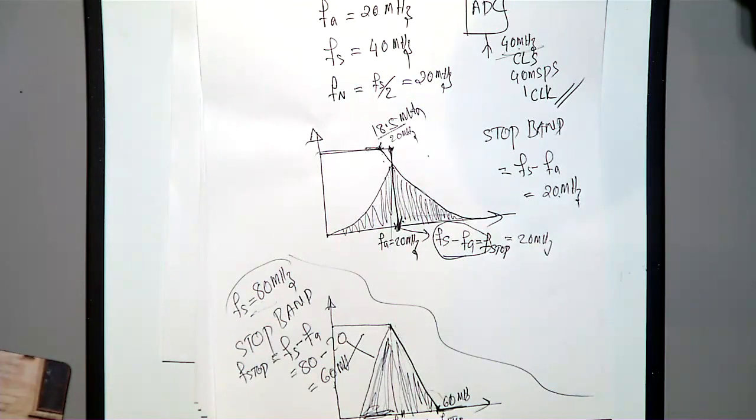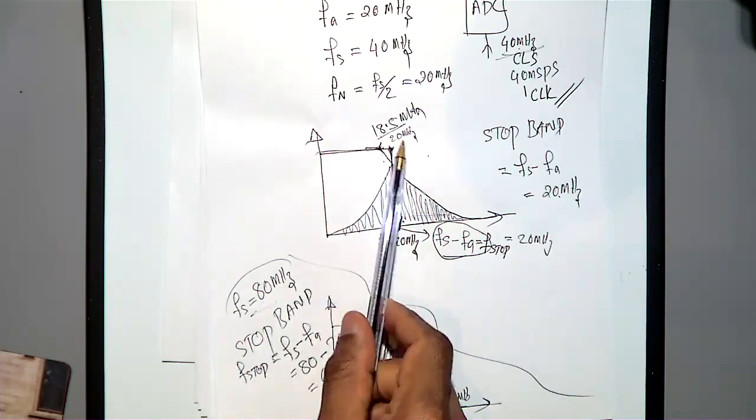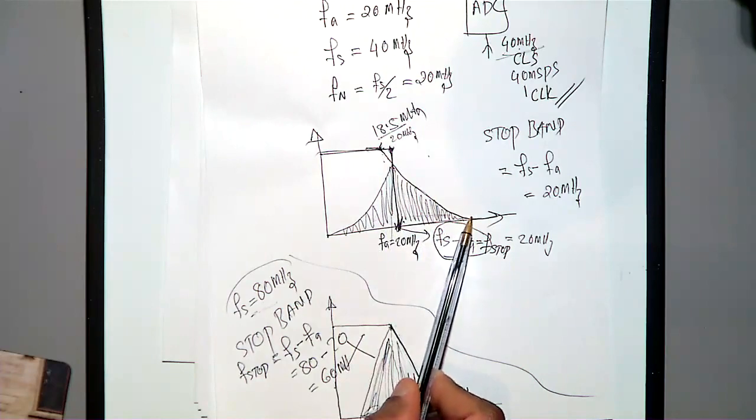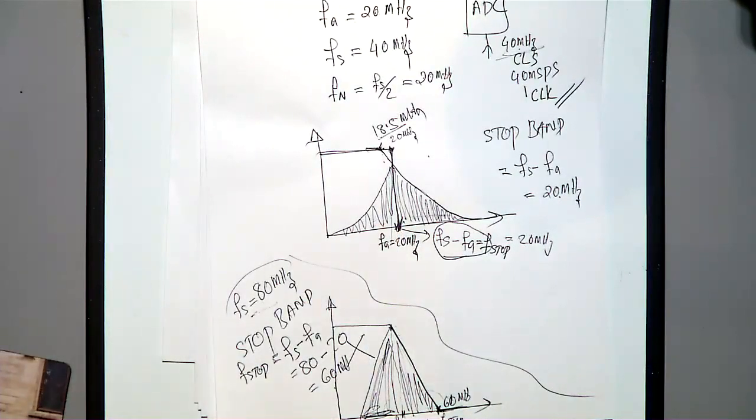So that is the reason you may have to put this 18.5, but then when you put 18.5, definitely your cutoff is much beyond your stop band. Your attenuation starts much beyond your stop band, which is okay in your case because you can't do anything else. But then within that one, how good you can design, that is the thing. I hope the filter design, everything, is clear.